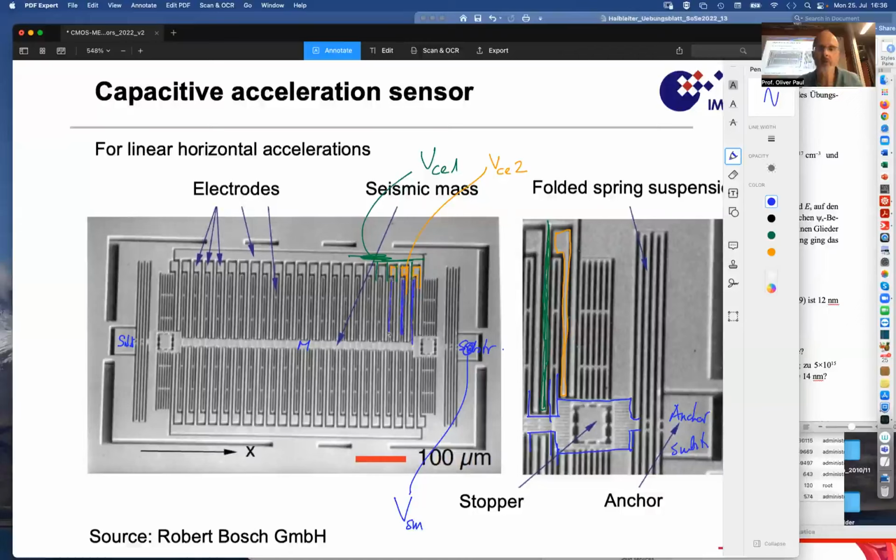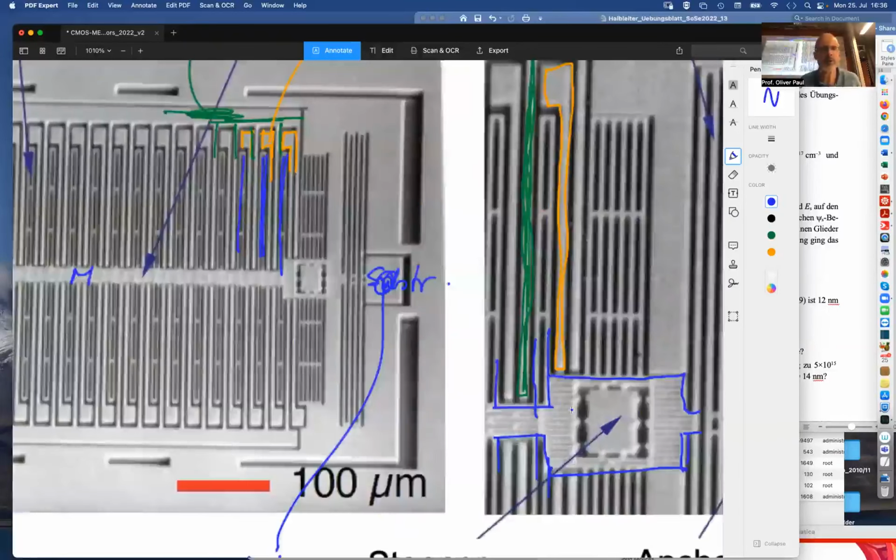So you may also wonder why these electrodes are designed like this, like these fine ribs, highly machined structures. The reason is that the mass needs to be light, and therefore removing as much material as possible makes sense. You also see that material has been removed here in this spinal cord, in this central frame element, where a complicated structure with all kinds of holes has been realized, so that there is as much rigidity for as little mass as possible.